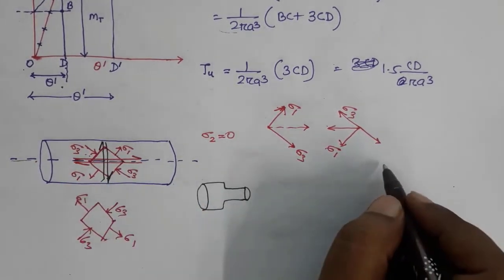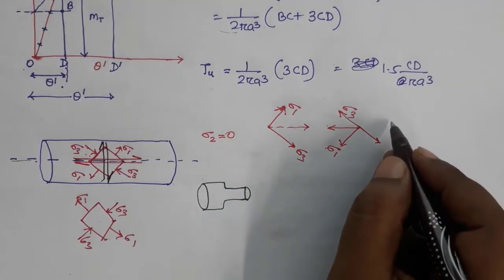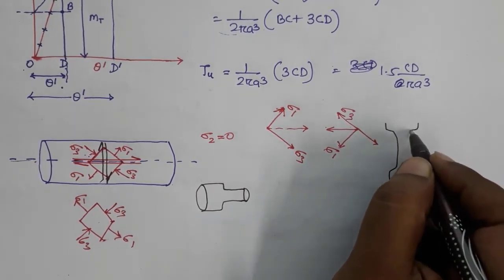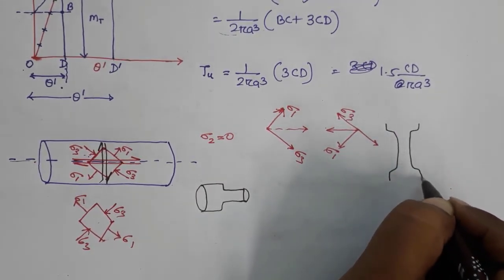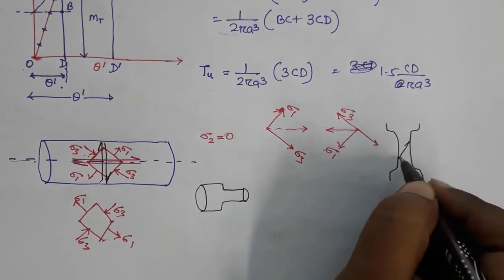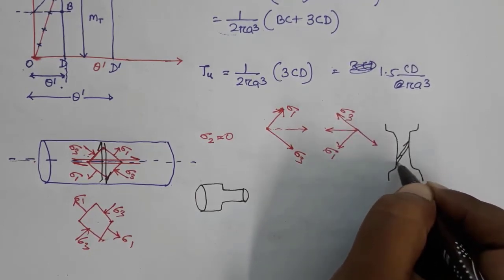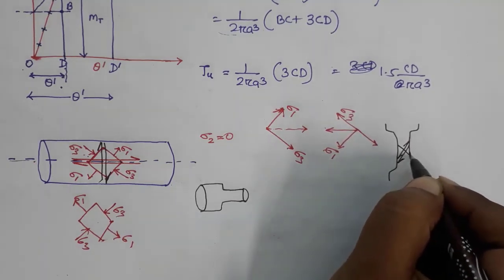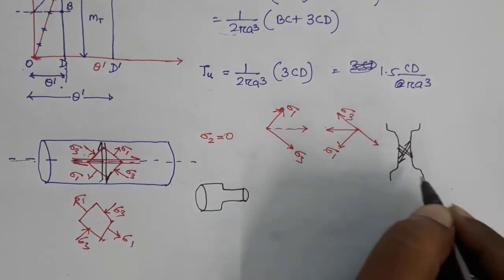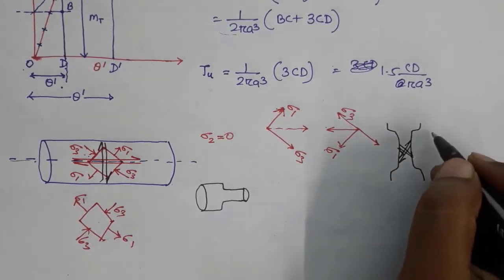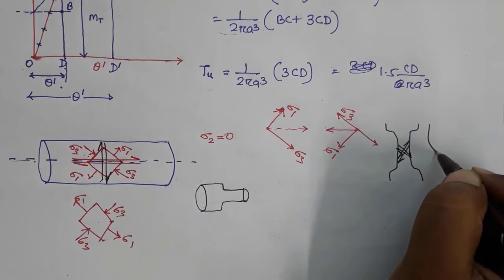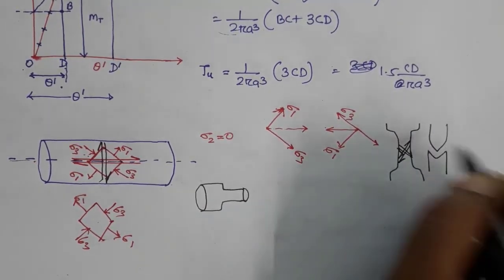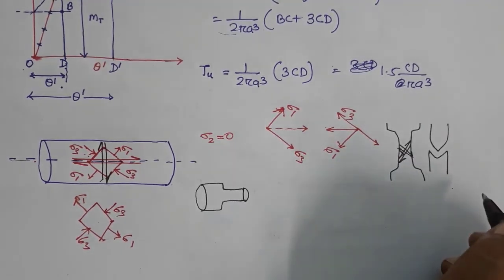In tensile testing, if you remember, how was the shear stress? So if the tensile test part was something like this, and in this case shearing will be in this direction, and in this direction, right. So this is why we got cup and cone type of fracture. So something like this and the other part was like that, and various combinations of these 4 directions, right.